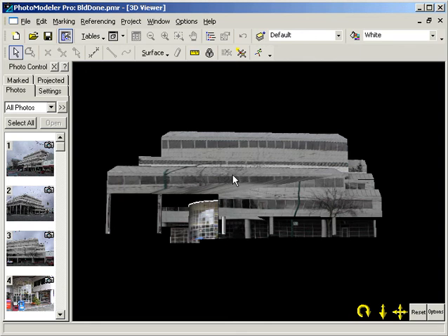Here we want to create an orthographic photograph of the facade. This is the end goal of this building project. An orthographic photograph is very much like this current view, a straight-on view of the building, but it is done at very high precision and at high resolution. An orthographic photograph, or orthophoto for short, is a parallel projection onto a plane of the model data with photographic information. It can be used as a type of drawing when printed out because it is to scale and you can do measurements on it.